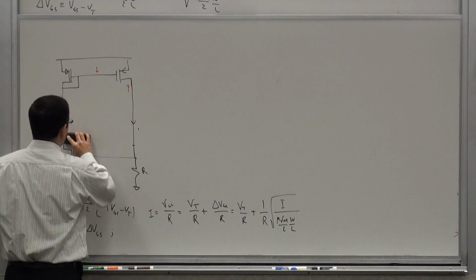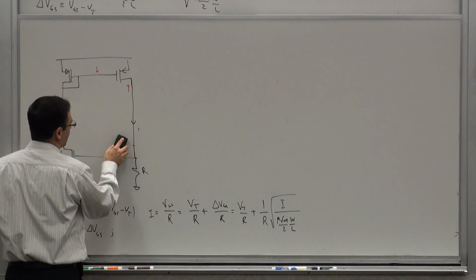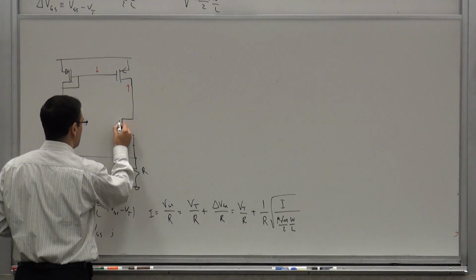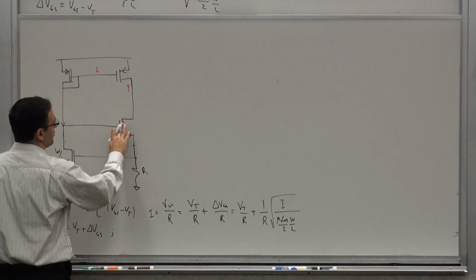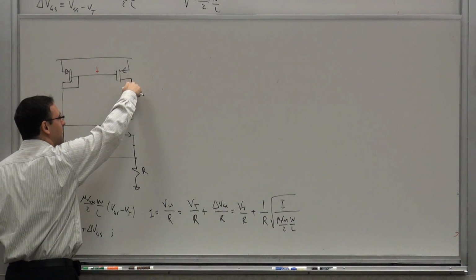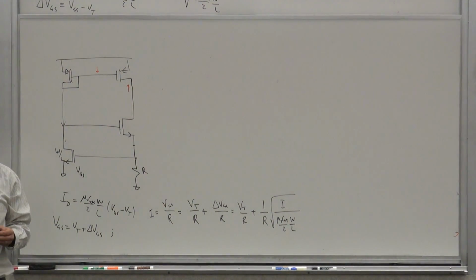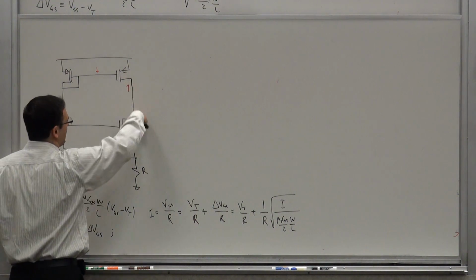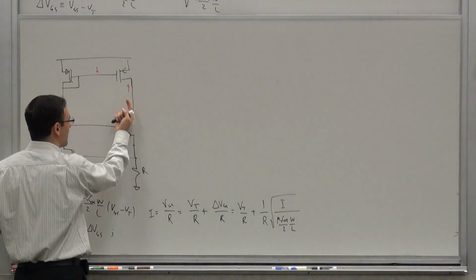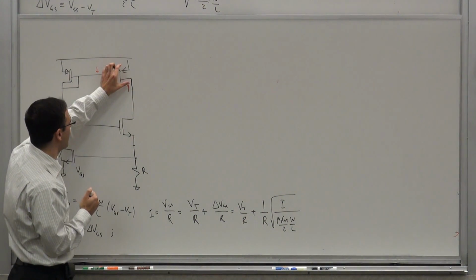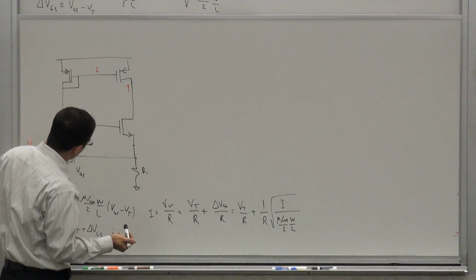One way to get around that problem is by basically just breaking this loop effectively by introducing a transistor here. So you can do this. If you introduce a transistor here, there's very little current, there's a little signal from here to there. The gain from the drain to source is very small. It's a reverse gain of a common base, or common gate. So there's not much signal traveling this way. The signal can travel this way, but not this way, because it has reverse isolation of this guy. So something like this, as simple as that.